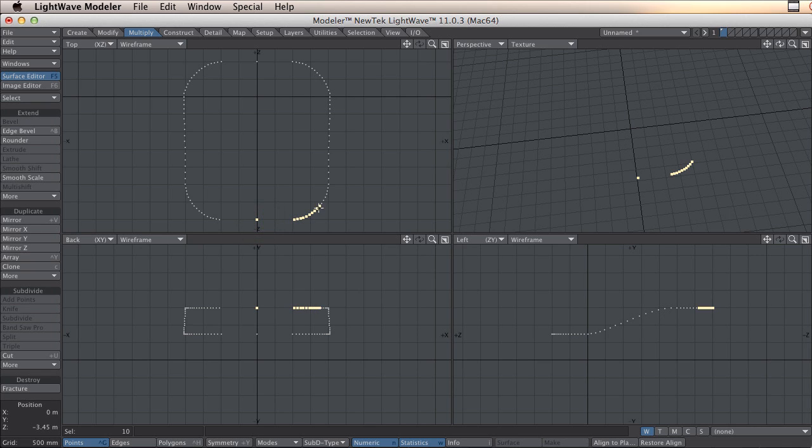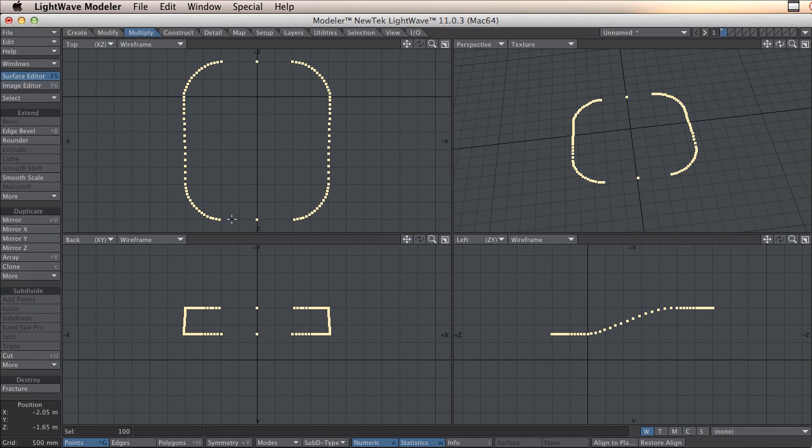If you draw all the points in one step, you don't have to do this step, but you need to do it later on, and I'll show you. If you jump over, go too fast, and you come here, you just deselect them and then press Shift and hold it down while you are dragging over the next point. It's very important to select these points in the right order, otherwise the car is going to go back and forth in a strange pattern.